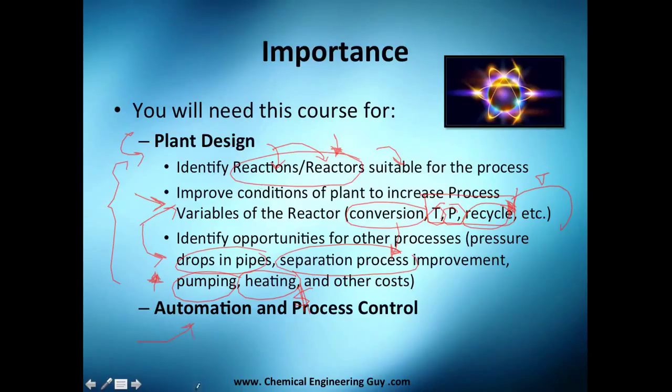And eventually comes automation and process control. This is more about having control of the process. So many times the reactor has temperature, level, and pressure limits, and you want to automate that. If, I don't know, you increase temperature, then you add an extra stream so it can lower the temperature, or if the tank is pressurizing and it's going to explode, of course you need to purge it so the pressure does not go up and explode.